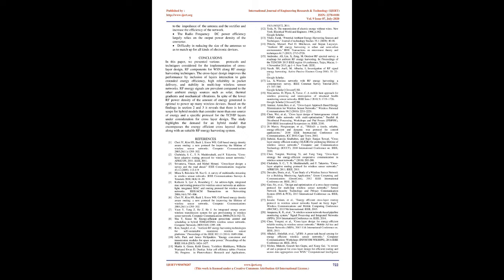Proposed a 4-stage threshold voltage compensated power converter to supply an increased power conversion efficiency, PCE, over a vast input power range that maximizes the area powered by wireless devices. The circuit is designed and verified using IBM 130 nm CMOS technology.